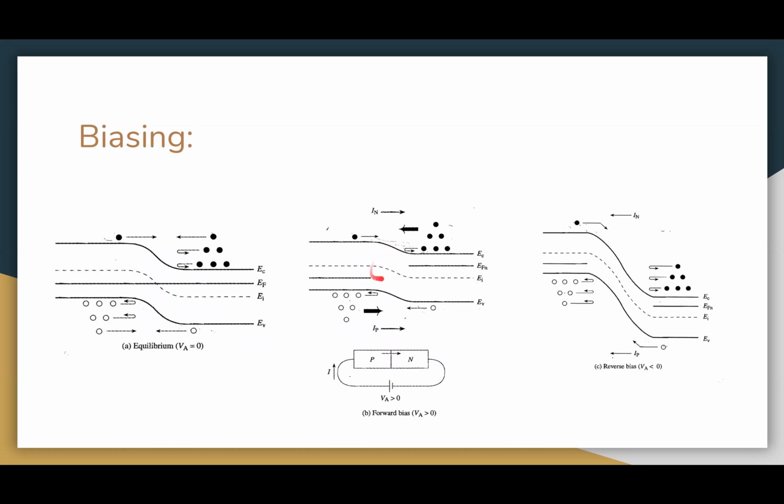So now there will be a current that's going to go across the PN junction. And as you can see in the picture, once the depletion region decreases, the energy level required for free electrons and holes to cross to the other side decreases, so it'll be easier for current to be present. Again, as shown in the picture, the top 2 layers of free electrons and bottom 2 layers of holes have sufficient energy levels to cross to the other side, and they're no longer being canceled out by the opposing junction. So now we're going to go into reverse bias.